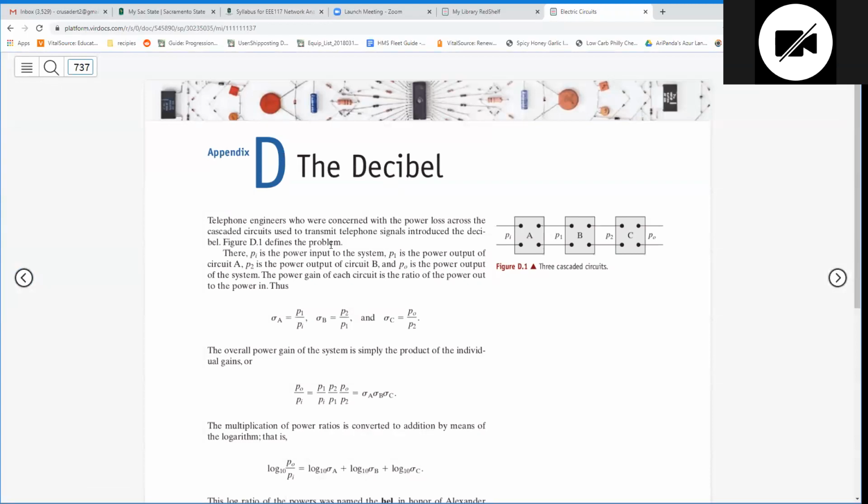Just to give you a little background, where are we at now? Remember, we talked about Laplace transformation this whole time. We learned circuit analysis, and we figured out transfer functions. Pretty much we realized that given the poles and zeros in a circuit, you could see the behavior of the circuit, whether it's infinite impedance, zero impedance, infinite voltage, or zero voltage. You get an idea of how the circuit works based on different frequencies, right?